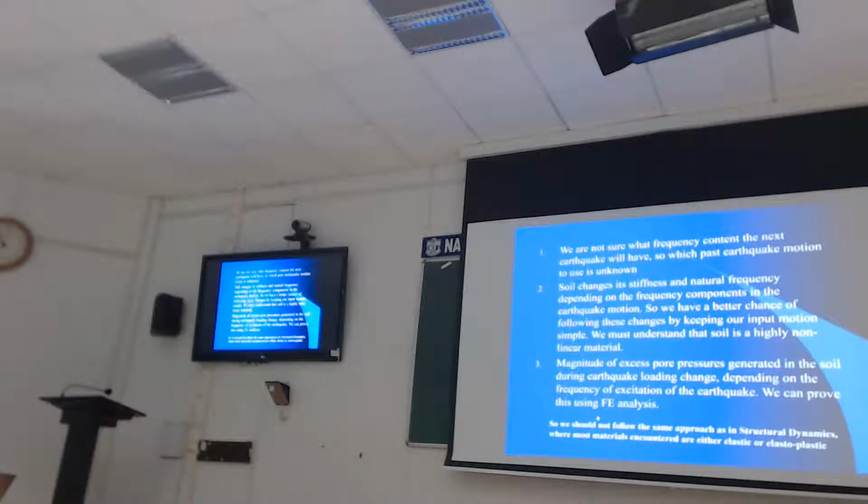I'd like you to think about the soil as a material. Soil as a material is quite complex. It's highly nonlinear. It goes plastic, or you mobilize plastic strains at really small levels of shaking, which means that the material is changing its characteristic as the earthquake waves are going through it.